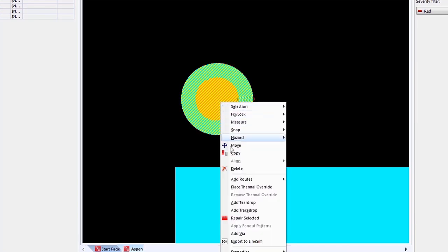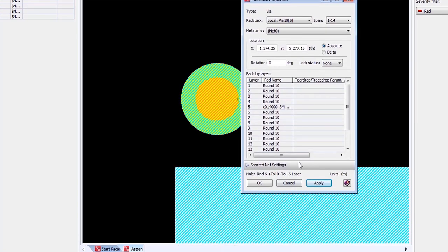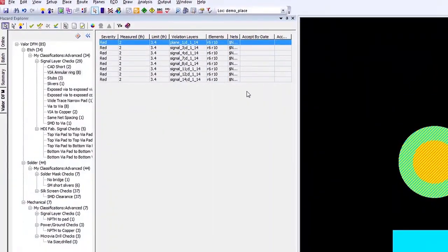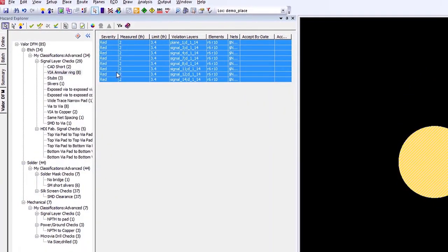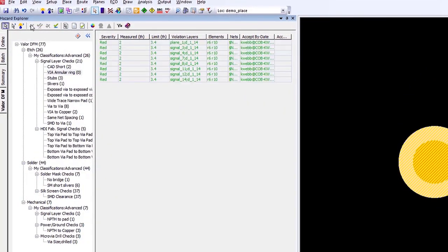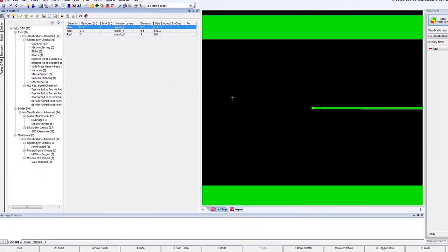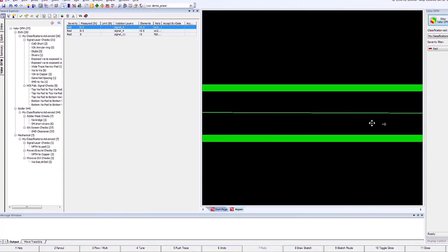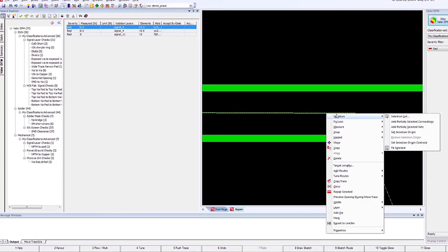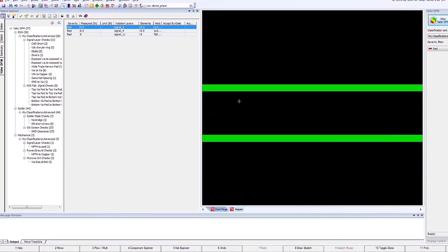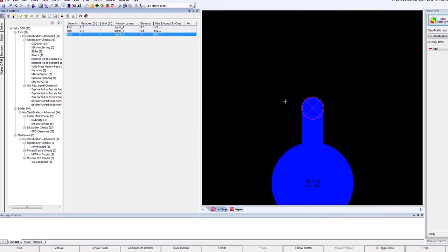We've just run the analysis, and now we can look at the results that are generated. All of the analysis is segmented into the different areas, for example, etch, solder, maybe component, and you can step through these issues and see live within Expedition as it takes you through each of the issues that have been highlighted.